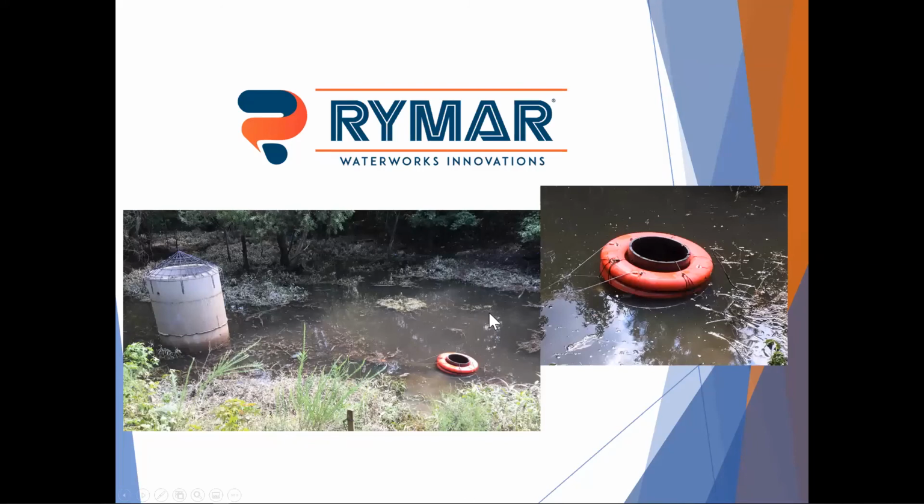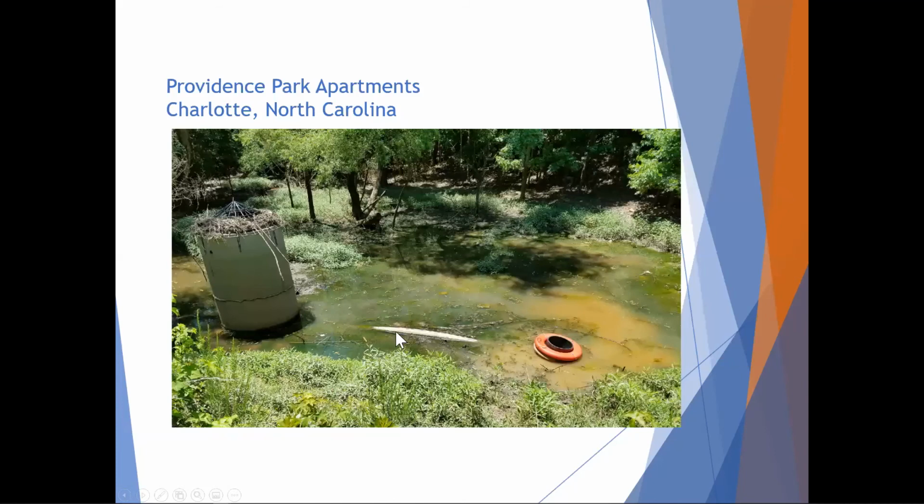We monitor it on a regular basis. It is in a natural area. It's a natural spring or stream coming to it. So it does stay wet from time to time if they have any kind of rain. But it is working. You can see here the riser has all this debris and junk up to the top of it, but with the storms, it still does drain down. And again, you've got the original pipe down at the bottom still doing some detention and not clogging, and with the trash rack and the skimmer, that pipe's not getting clogged. So a very successful use of a skimmer for permanent maintenance with the added benefit of stormwater fee credits.